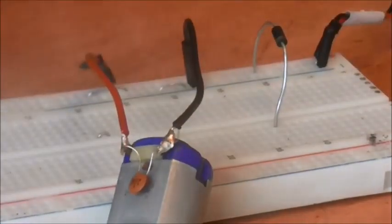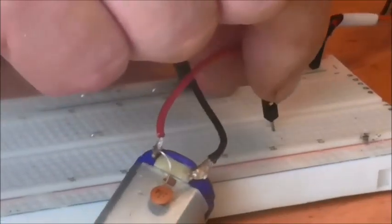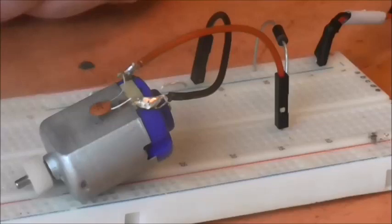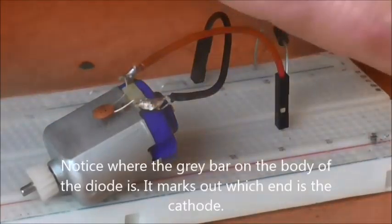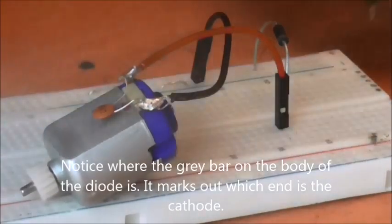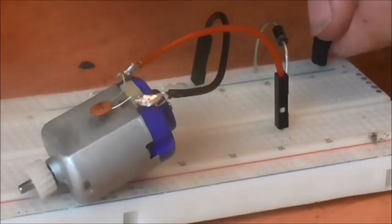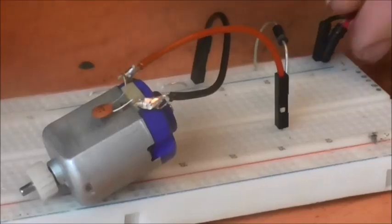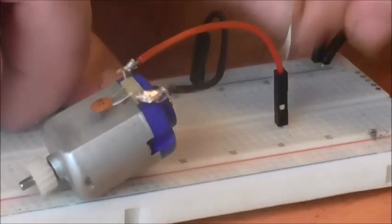And now I'm going to put the red wire from the motor facing the cathode of the diode, and the motor starts to spin. What I'm going to do now is turn the terminals around so that positive is where negative was and negative is where positive was, and absolutely nothing happens. However, if I turn the diode round,